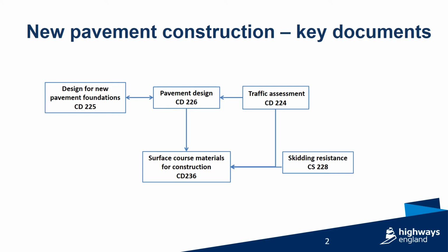CD 236 requires the data gathered from CD 226 to select aggregates with an appropriate resistance to polishing for a particular site and traffic loading, and should result in a surface giving wet skidding resistance above the appropriate investigatory level assigned in accordance with CS 228.